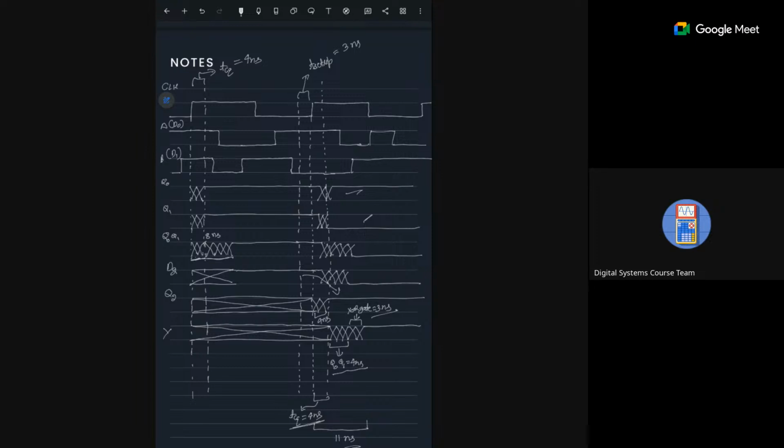TCQ time is not considered for that one, na? Wait a minute, I'll tell you. It is not a flip-flop delay. It is a clock's TCQ. Yeah, the time it takes from the clock's edge for the data to appear at the output, right? That's TCQ. Because in the lecture, the professor said for every flip-flop you add to the pipelining system, it will increase your latency because TCQ adds up. I think it was in lecture number.